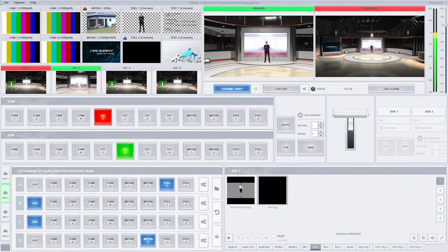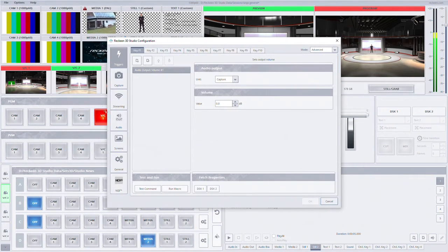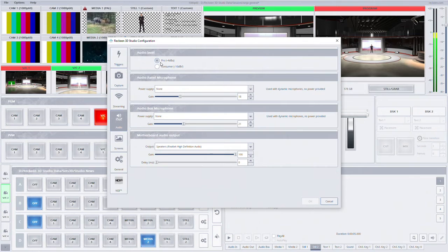In the next tab, Audio, we can find settings of the system's sound. There are 2 levels of the line signal to choose from. The first one, Pro, is a professional one where level 0 has a value of +4 dBu. This signal level is the most common for the XLR connector and for the TRS connector, that is 6.3mm stereo jack. The second signal level, Consumer, has the 0 level for the value of -10 dBV, and it is most common for the RCA connector, commonly known as Cinch.